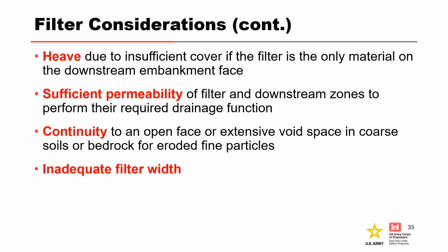Additional filter considerations include heave due to insufficient cover if the filter is the only material on the downstream embankment face, sufficient permeability of the filter in the downstream zones to perform their required drainage function, continuity to an open face or extensive void space in coarse soils or bedrock for eroded fine particles, and inadequate filter width.